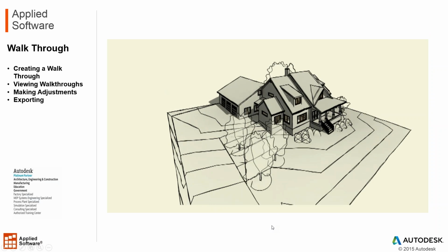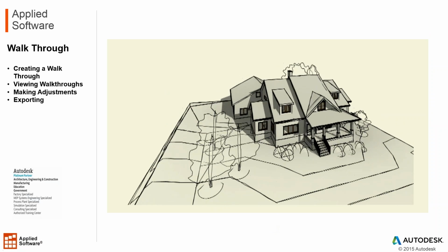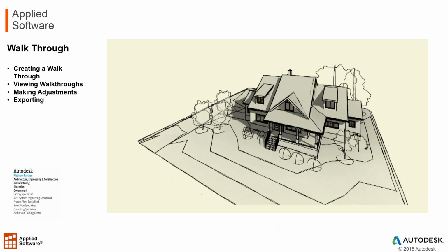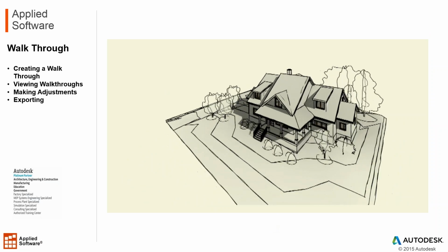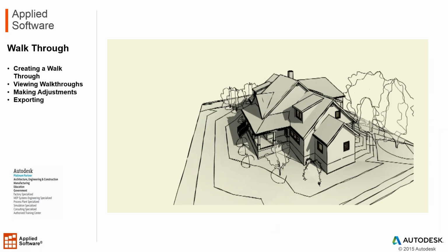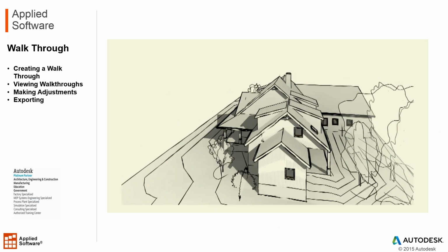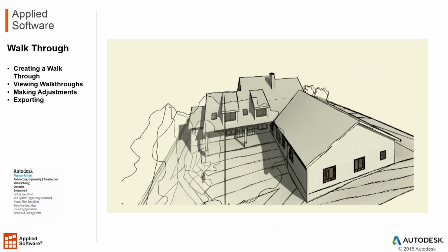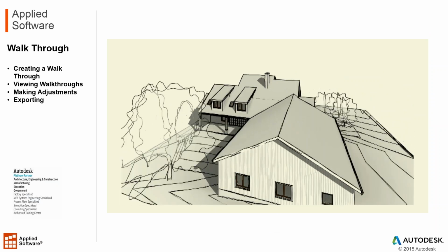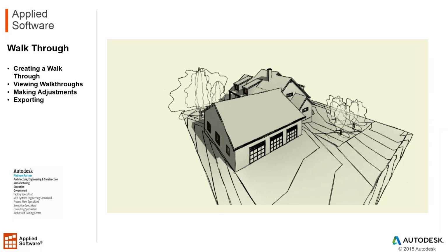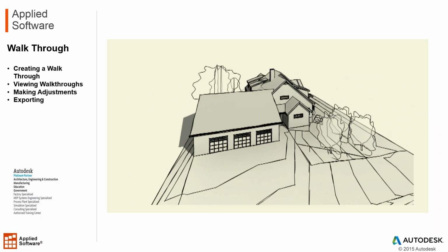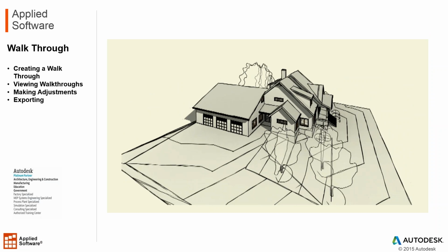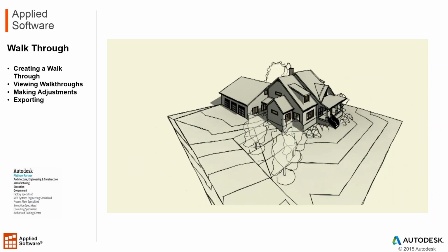And then you can do walkthroughs. This is a video, though it's not really a walkthrough; it's just a spin around, but I used the walkthrough command to create this. I just drew a path up in the sky, an oval path around my building, and it instantly created this video file. So again, a great way to give an overall view of the project so they can see all sides of it. You can stop this video, pause it, fast forward, whatever you want to do.